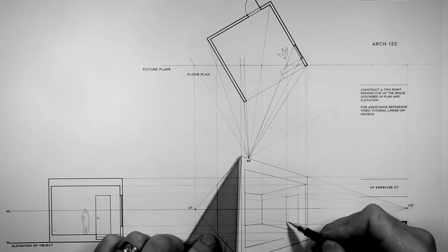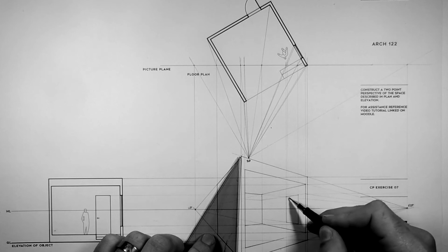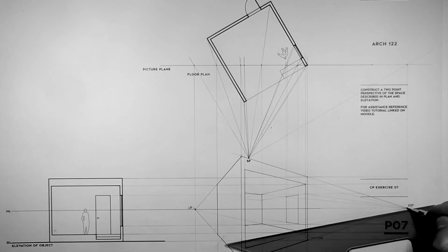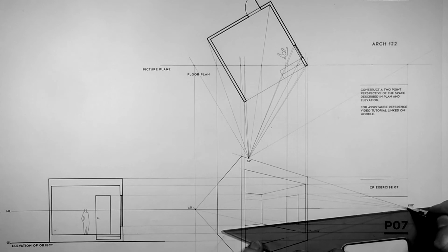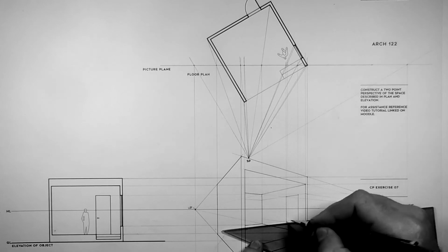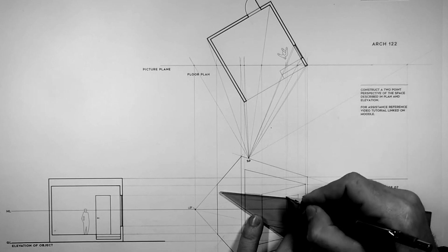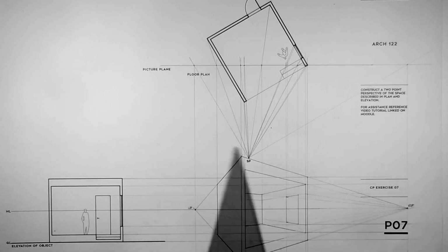Before we describe this vertical thickness, we need to project the depth in this bottom left and top left corner. So for that, moving in that direction, we'll use the right-hand vanishing point, and we will darken that line just a little distance to represent the thickness of the wall. Same thing there.